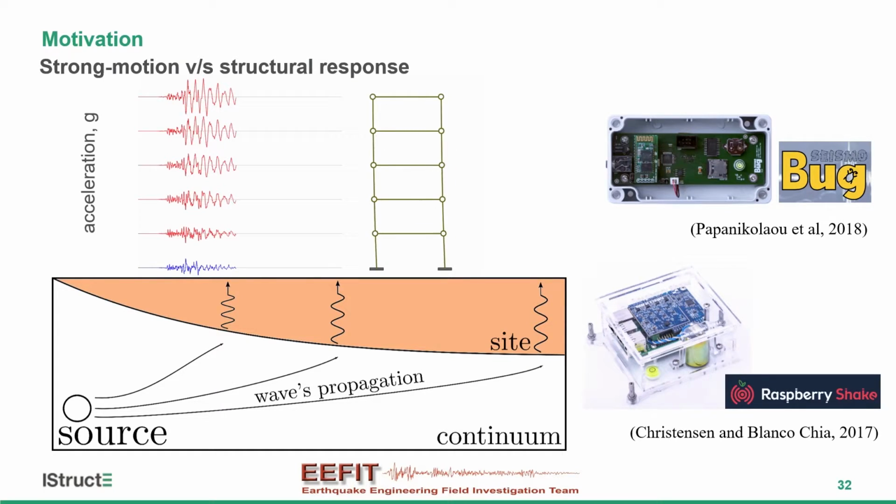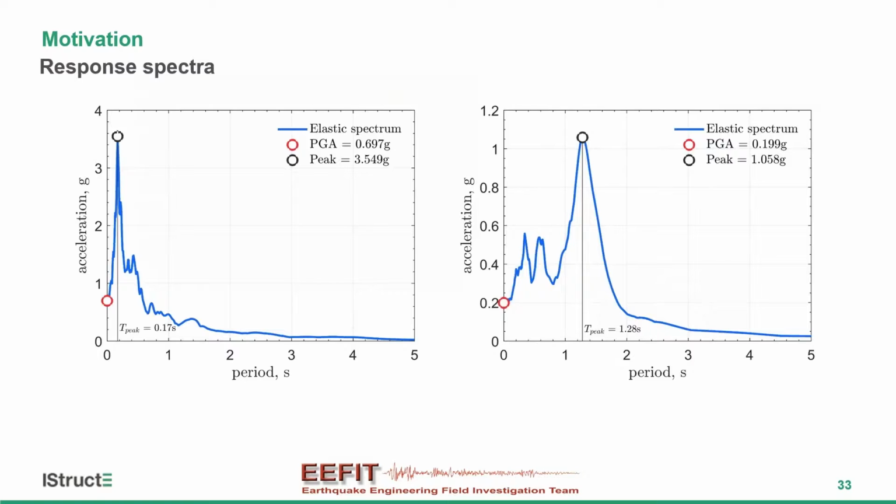And the main difference is actually the amplification, in this case of the acceleration. This is actually the real scale and undistorted real response of a typical shear building. So you can see that as you start going up, you have amplification of the acceleration. This is something that we know, and we've compacted it in the response spectrum that we are super familiarized with: the response of a family of single degree of freedom systems under a specific earthquake. So we have one of those for each earthquake.